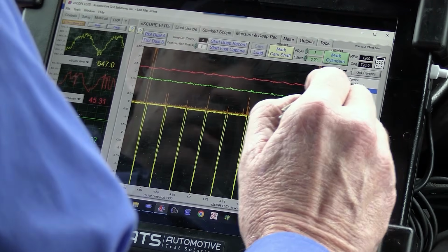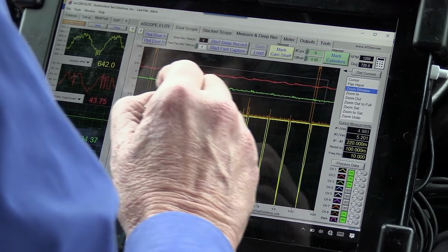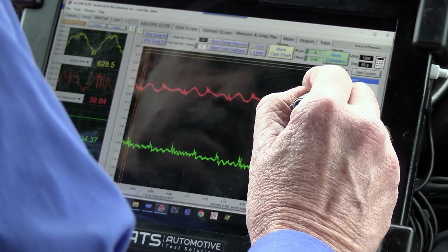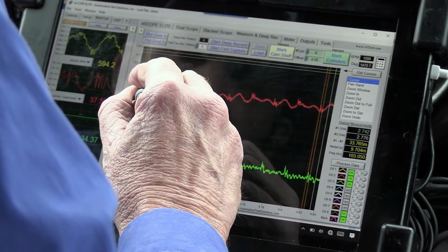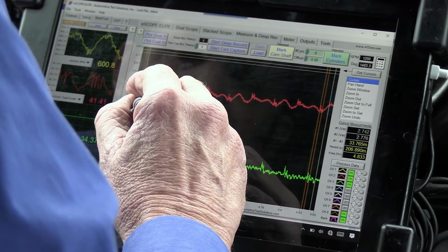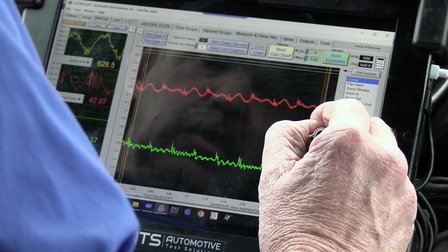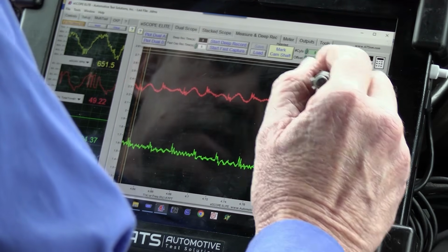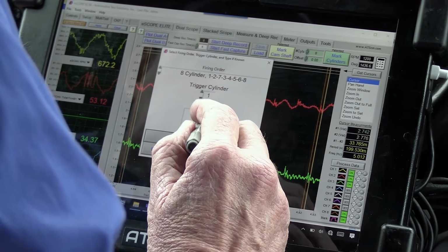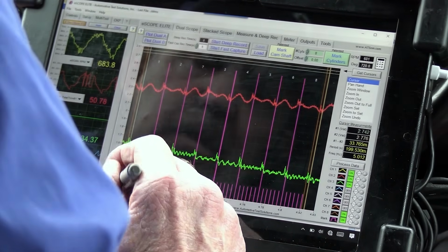So let's get our zoom window and let's zoom in on this waveform that we saw before. I want to make sure that it's still failing the same way, that every other one is failing while we have good amps. Because the amps are good right there and everything looks good. Let's make sure that the rest of it's the same. So we're going to mark this. Okay, that shouldn't be on intake. That needs to be on ignition.